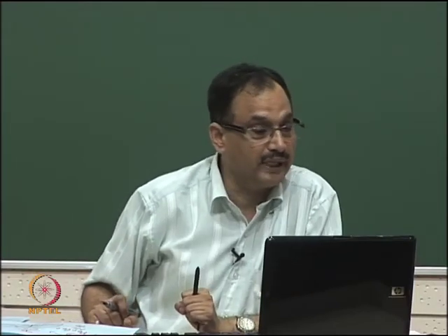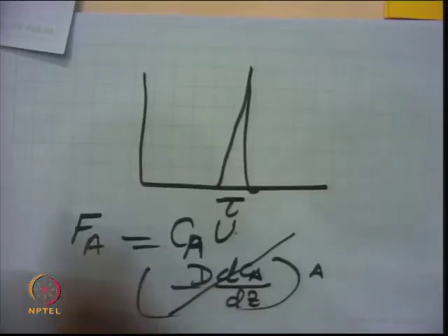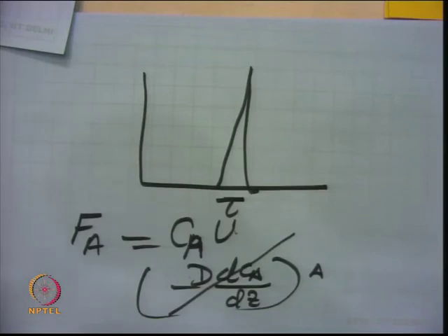That is why I said small tubes when you do the lab reactors, right. And same thing, when you have an axial dispersion term, it will depend on the height of the catalyst bed, right, and the tube diameter. It will also depend on the size of the catalyst particle. So, all these are important.